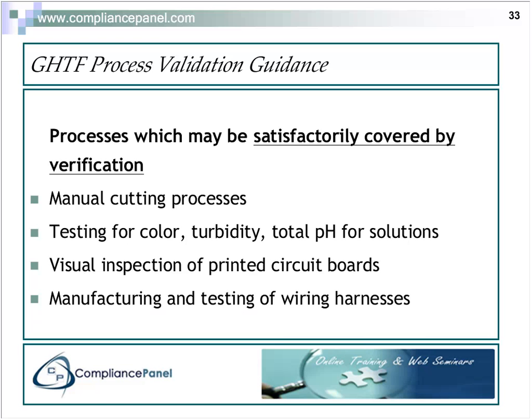Manufacturing and testing of wiring harnesses. Now, you can do that verification. There are plug boards where you test this wiring harness and you push some buttons, and it measures to see that there is continuity between points and there's a lack of continuity between places where there should not be continuity.